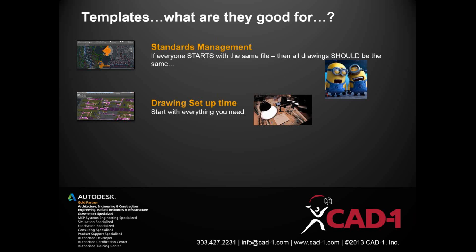A user starts a brand new project, starts a brand new drawing using a template. What do they have to do? They got to draw. They got to design. They got to draft. They don't have to worry about any of this management nonsense, any of the drawing setup. It's all taken care of for them. It's sort of like what we like doing with programs like Civil 3D and the AutoCAD architectures. Like with Civil 3D, I want to draw an alignment. I just click alignment and start to design. I don't have to worry about layers. I don't have to worry about any of the rest of that. It's all taken care of for me. You can do the same thing with templates. Start with everything you need.